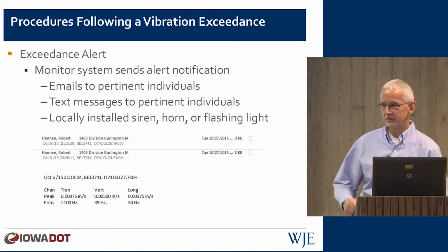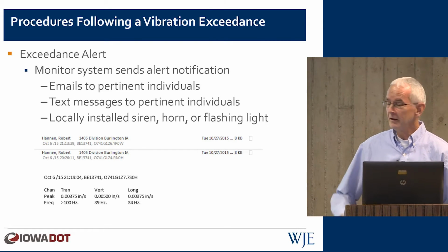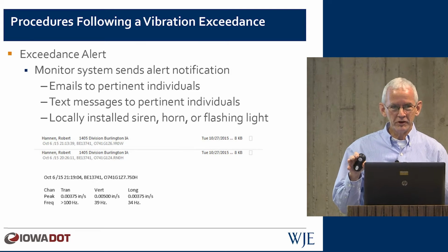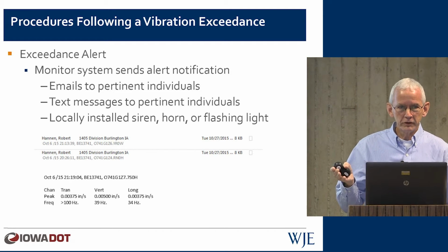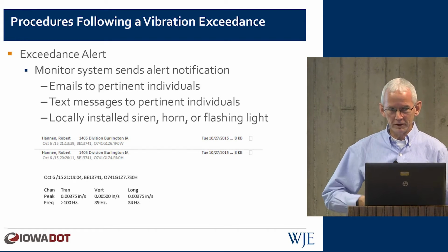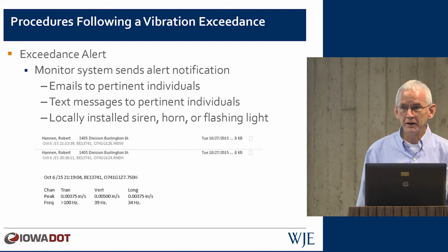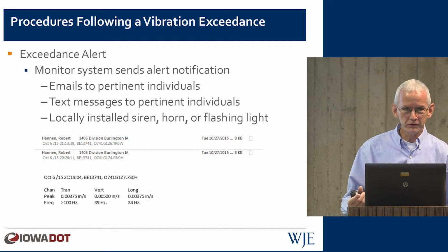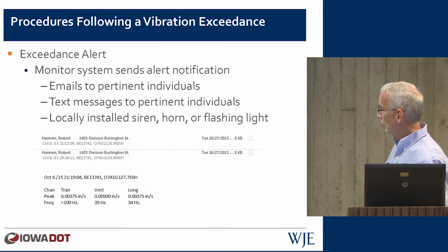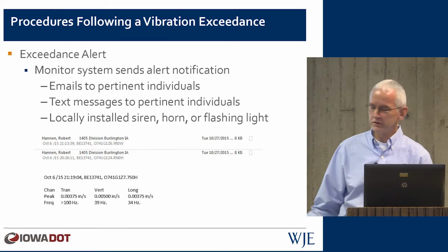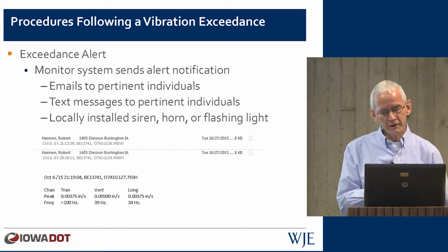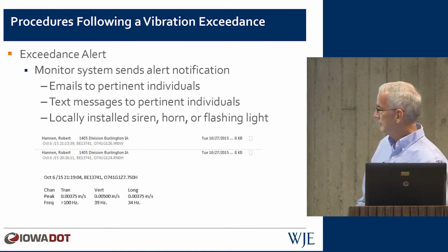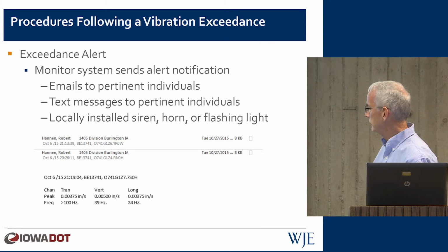When the seismograph is continually collecting its data and evaluating the frequencies, if the frequency of the vibration is higher than 100 hertz, it doesn't try to evaluate it. It just says it's too high. It's scanning at 1,000 hertz. It should be able to go up to 500 hertz, but it doesn't really report anything if it's greater than 100, so it just gives you that indication. But that lets you know that that vibration is a very high frequency and would not be significant to the structure.